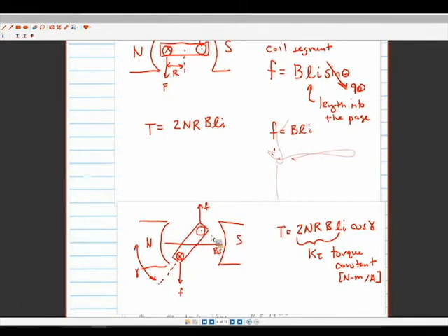Yes? So, two questions. So, like, torque, normally it's a force and a lever arm. Why are we including the number of coils? So the number of coils determines how much force you get, right? So the first equation here is the force on a single wire, right? And now we're going to loop n wires around. So if you take a look at the motor that's right around the room, you don't see just one wire making one of the loops, right? You see a bundle of them. Okay, so one gives you 1 unit of force, two gives you 2 units of force, and so on.